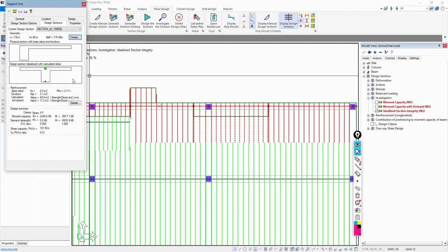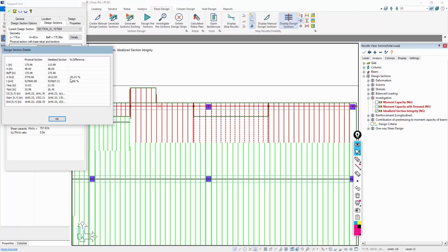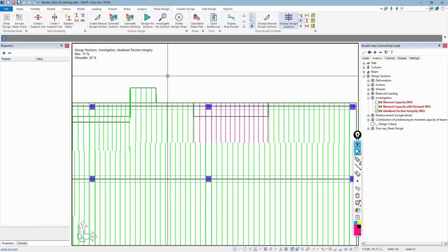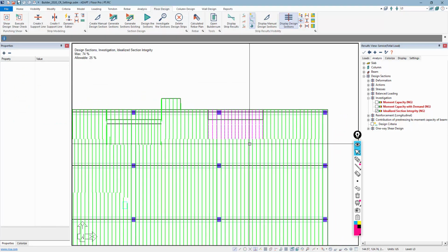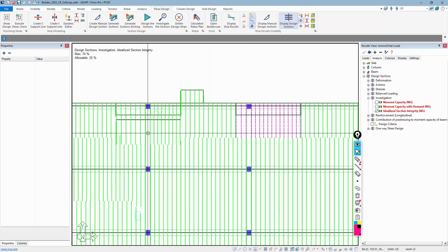And so we get very little difference if we were to evaluate both for the calculation of rebar and the calculation of stress. Back over here in the problem area, if I look at the percent difference, it's 42% for the area. The moment of inertia is actually 0%, but the area is 42% difference. So that flags this section. And we say, well, how can we revise this to make this more accurate with the design?